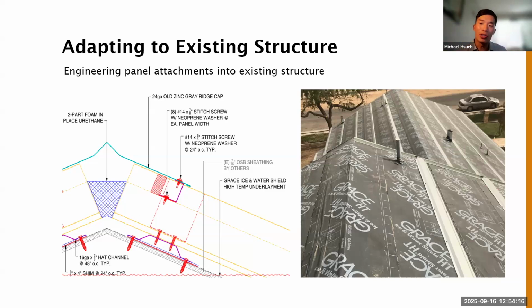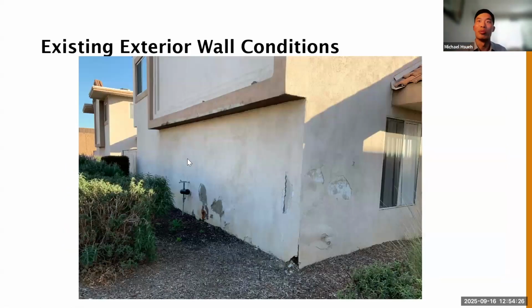At the wall panels in Corona, we used a similar strategy. That one was much more difficult to manage because, I'll pull up the photo again, this is the substrate that we're working with. It's not very flat. Across one whole elevation of the building, the in and out from one end of the building to not even that far away could have been as much as an inch and a half out of plane.